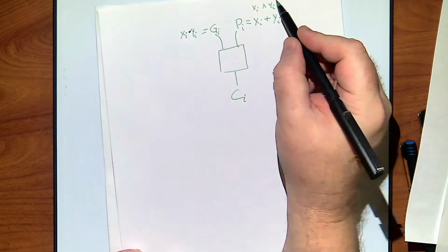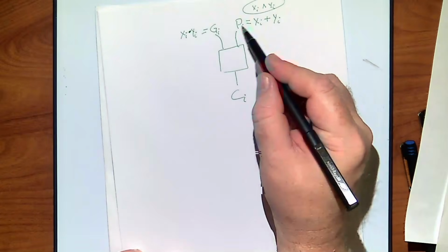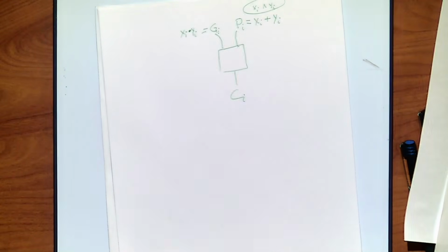If you want to be very technical, propagate is defined with an or, because it means if there's ever a carry below it, that carry will propagate. If I wanted to save space, I could replace it with an XOR and just take the half adder and generate take over.